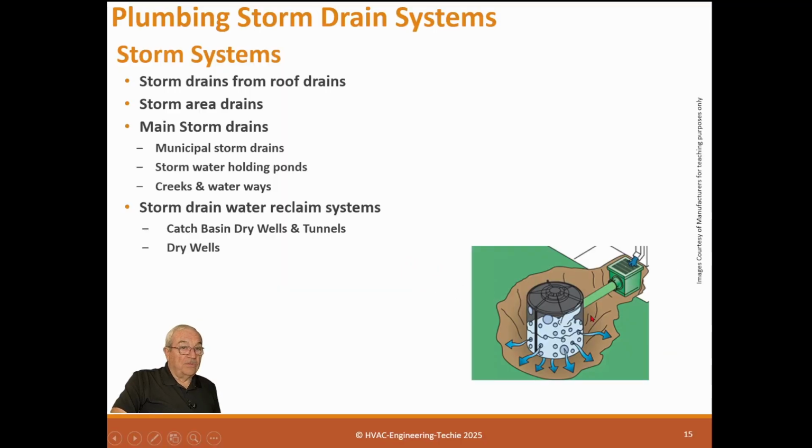Well, we have dry wells, and a dry well basically is used when you don't have a whole system. The water flows into this manhole, or we're going to call it the dry basin, and it has gravel at the bottom of it, and it holds it and lets it seep out over time into the adequate surface. The only problem with these is you got to make sure that people don't put anything here that's going to contaminate or seal this gravel down here.